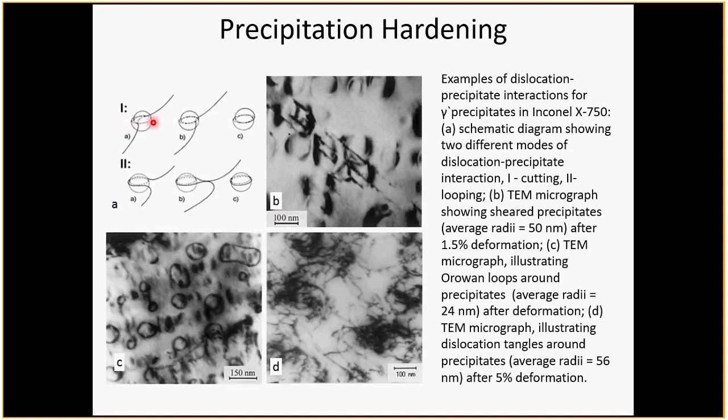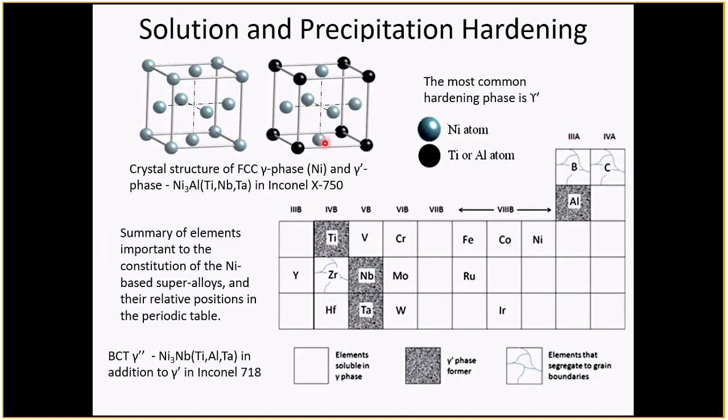So in order to pass through that precipitate, create this antiphase boundary, that has taken extra energy, and that's what, as I say, is the essence of the impedance, because otherwise it's still an FCC phase. Why should it hold it up? Oh, there is one other factor. These gamma prime precipitates, they're typically a little bit different in volume.